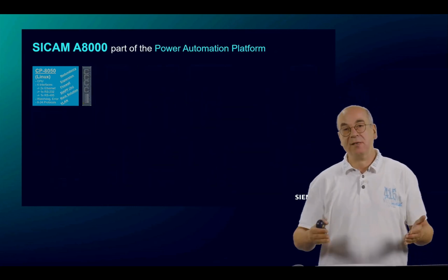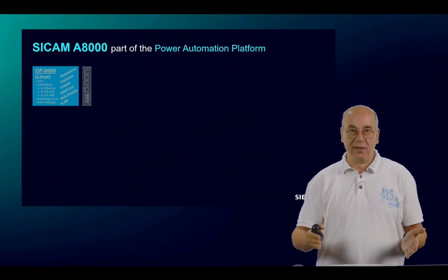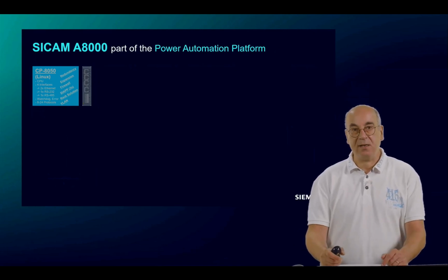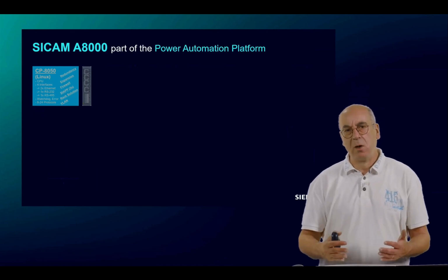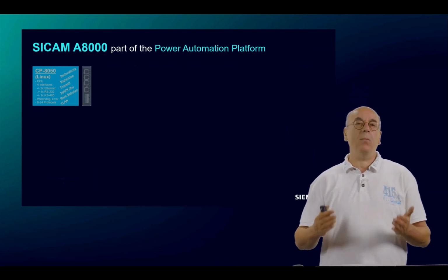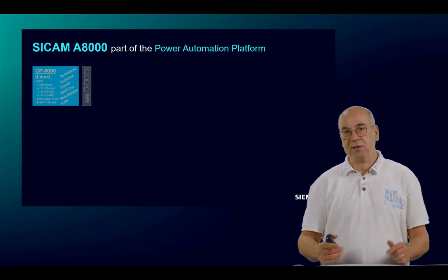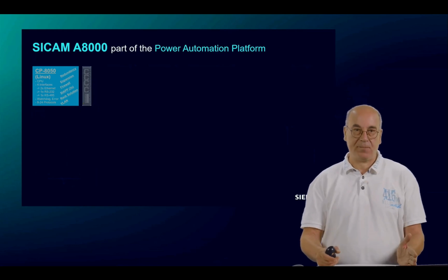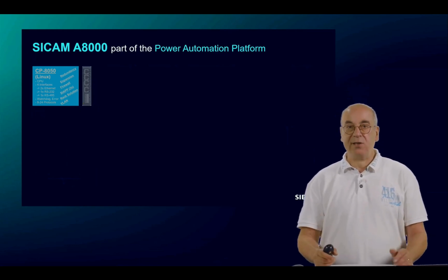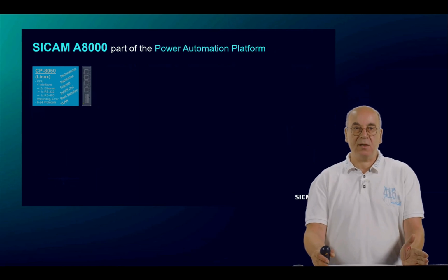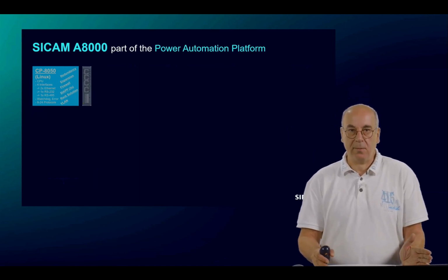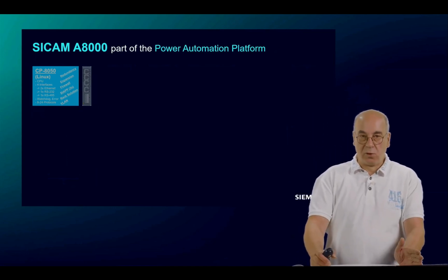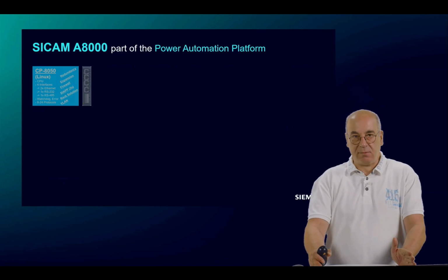Okay, coming now to the CP8031, also Linux-based and therefore part of the SICAM 8 platform. The CP8031 is using a very similar powerful processor and memory features. Most of the functions I introduced for the CP8050 are also possible. Therefore, I will focus only on the differences. Redundant RTU controllers are not supported with the CP8031. The CP8031 allows loading up to 4 protocols, and not more like the CP8050.